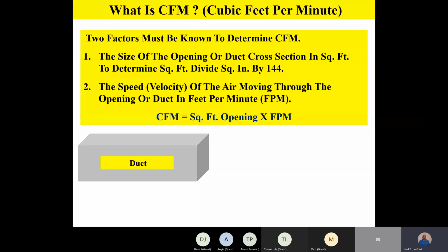So if I took 100 feet of that duct and put a fan on the end of it, and I was blowing 500 CFM through it, and we measured the static pressure loss on that fan, we'd see that it would be about a 0.035 to 0.040 inches of water column external static pressure.